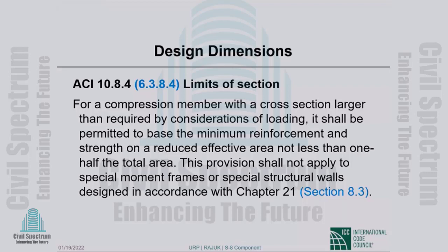This is extremely important because let me tell you something. We never, basically never design a column. We design a column stack. If it is a 40-story building, we design a stack of columns that is 40 stories tall. Okay. Now, from story 1 to story 40, we are not going to change the cross section of the column 40 times as the axial decreases. That would be